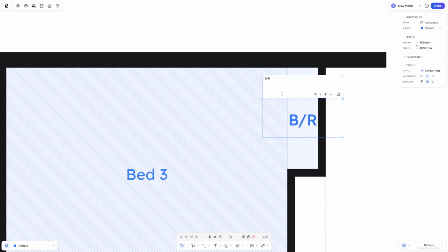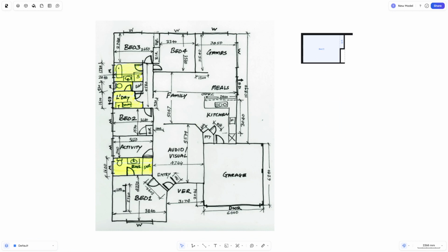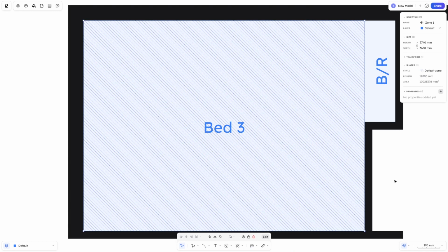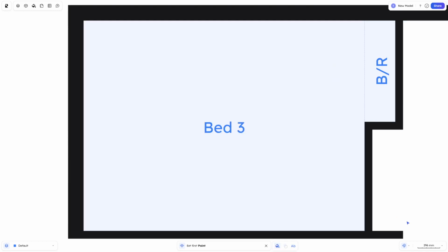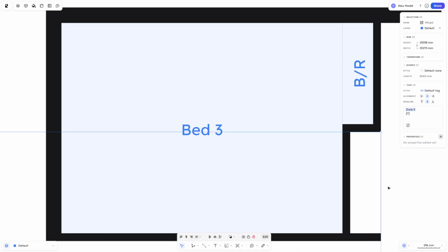and we're just going to replicate exactly what's written on the previous floor plan. So rotate that around, shift F back out, and you can see they've put it there. So we should be able to do the same for here. Let's go back in again. Put a zone divide in. Why is that not snapping to there? There it is this time.